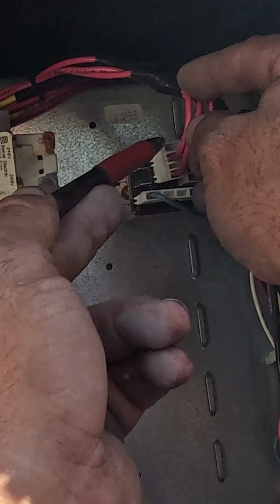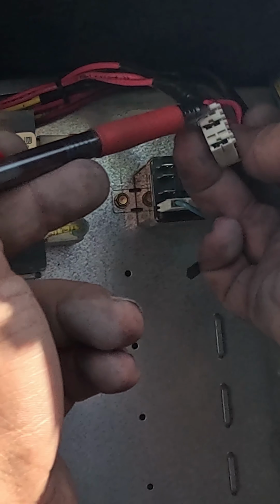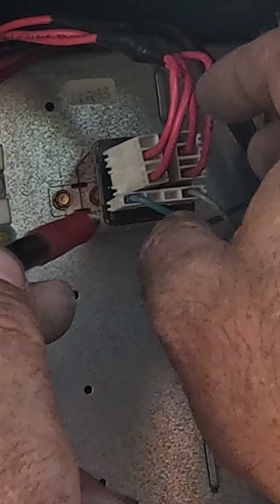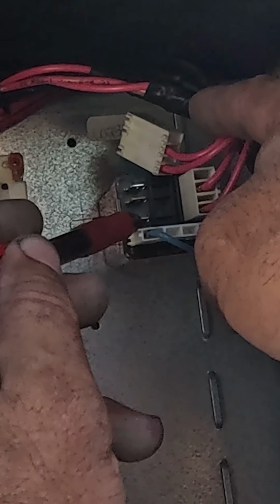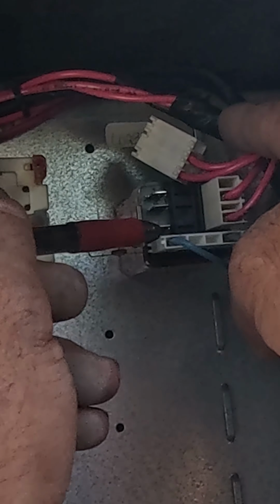So if we unplug this relay here, you can see that even though we only have these wires connecting, there is 3 spades. So if this one did have that crankcase heater, there would be another wire in this top one to plug in right there. The way a relay works, you have coil voltage. One of these will be normally closed, and in this case, this will be our common leg. So no matter which one of these opens or closes, this will either connect to that one or this will connect to that one. Normally closed on this one is from here to here. When we get coil voltage here, that's going to flip. Then this voltage will now connect to here, and that one will be open to nothing. Hope that helps.